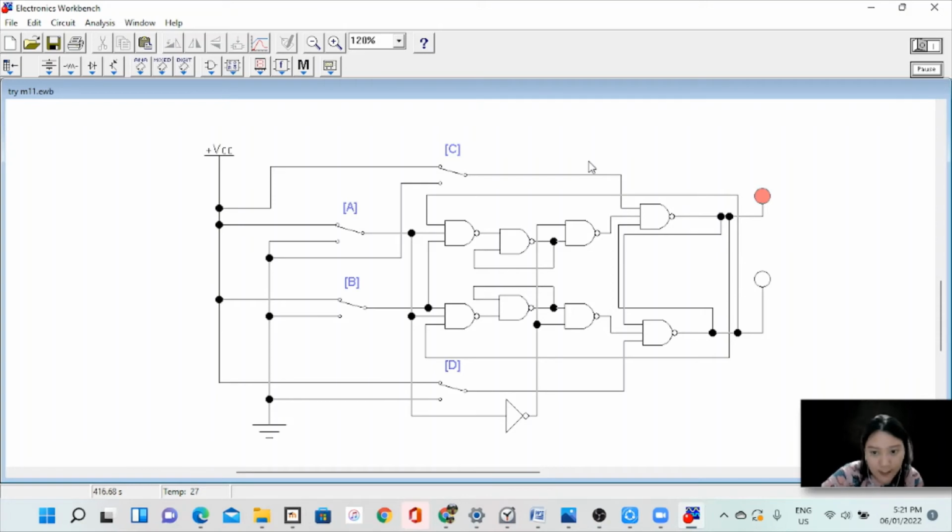And now what will happen if we set the clock to high and switch letter A or the toggle from high to low? So our output toggles. Now we're going to check this with our truth table. If the clock is at low and our T is at low also, then the output is on hold.